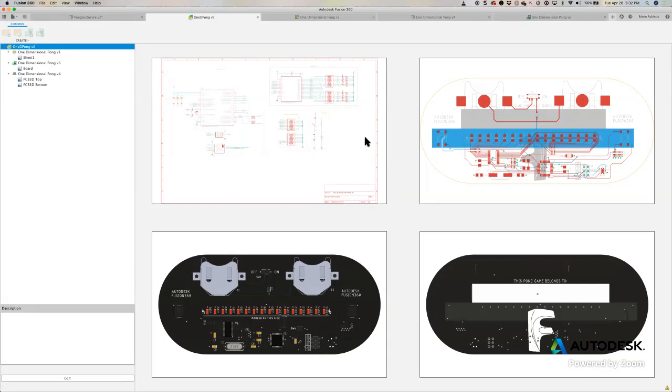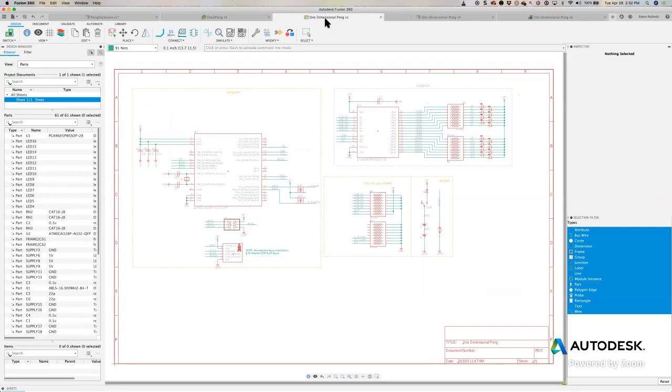Managed libraries are the method by which it allows you to access your libraries remotely, and it also gives you the capability of assigning 3D models to your components. Okay, there's many ways of doing it through a package calculator. You could assign STEP models to it, or you could access our repository of 3D models for each component as well. Well, in Fusion 360, we can access managed libraries.